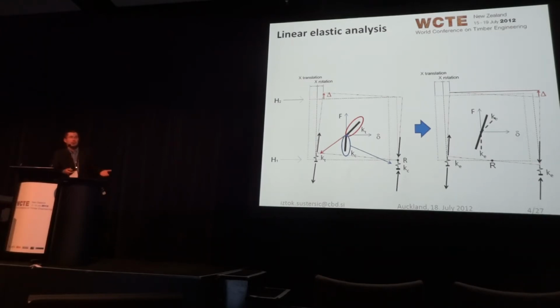Therefore, it allows for a unified matrix, if you want to call it so. But the basic idea is that the rotation, or the translation we get from rotation, in the properly modeled load case, the properly modeled wall, equals the one that we get at the recalibrated situation. Now that's quite tricky and a painstaking procedure, so later on I shall be showing you a new procedure that we've come up with that simplifies all that.